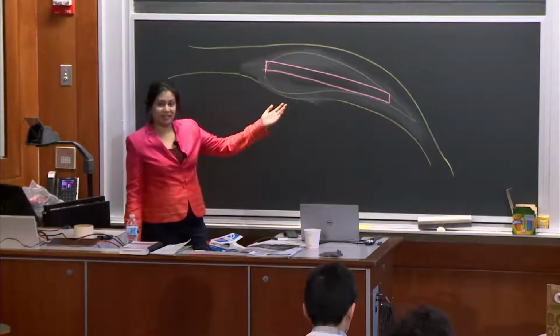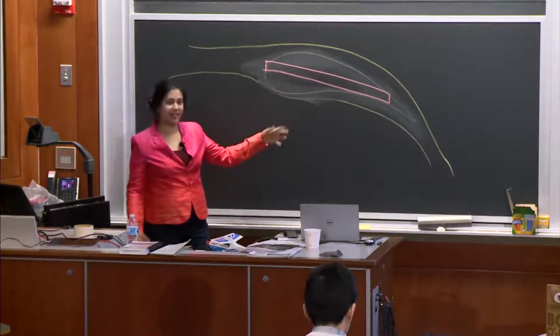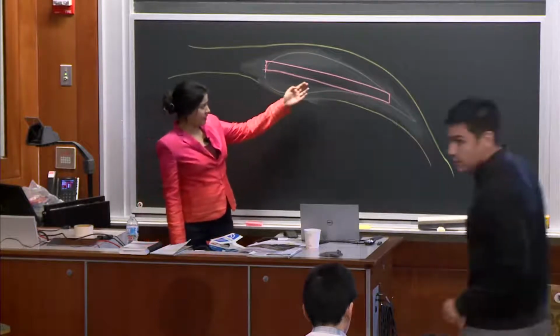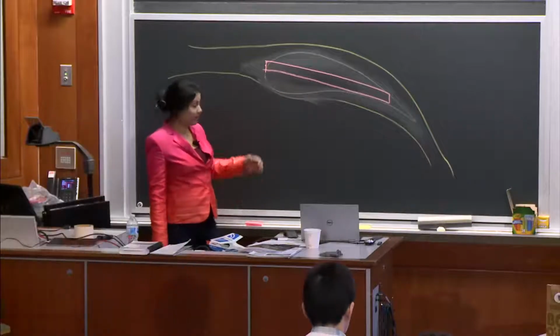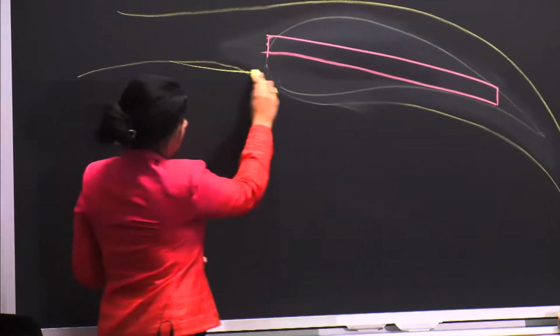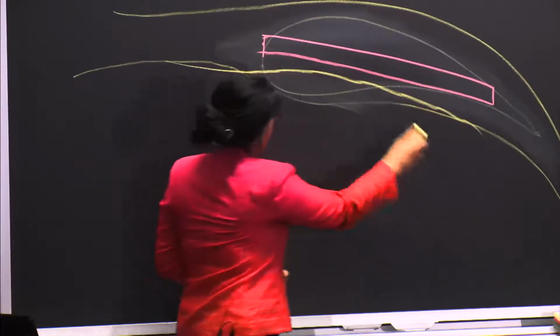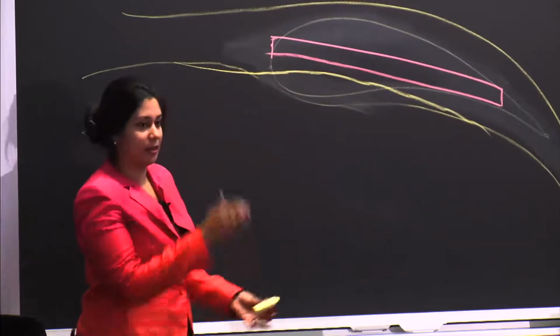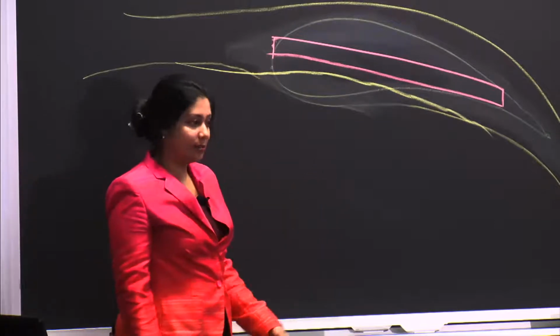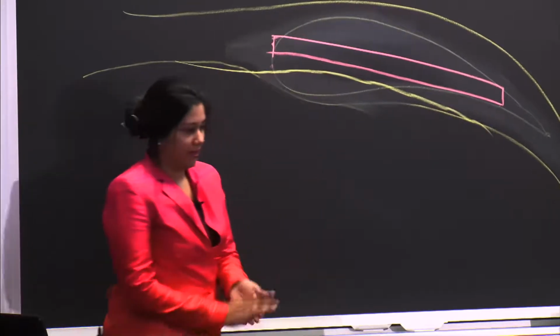Yet, a paper airplane still flies. So why is that the case? Again, remember the actual reason: if this paper airplane is inclined, it is pushing air down. So air that's coming up is bumping into it and being pushed down. And therefore, as you deflect air molecules down, by conservation of momentum, the wing is lifted up. All right.